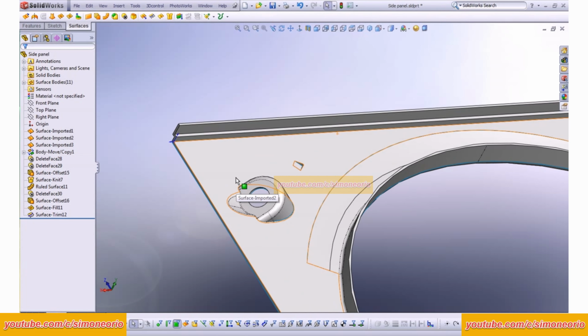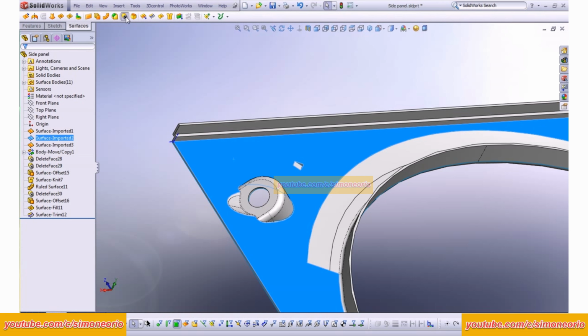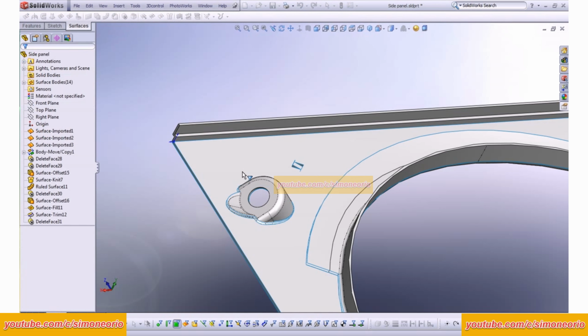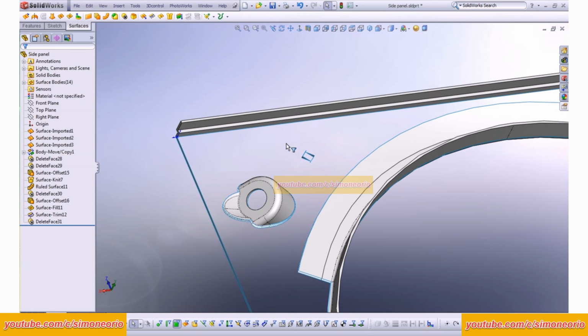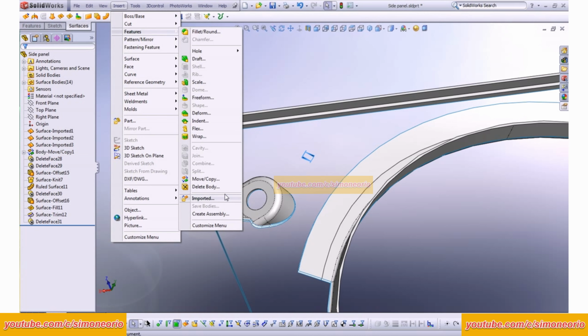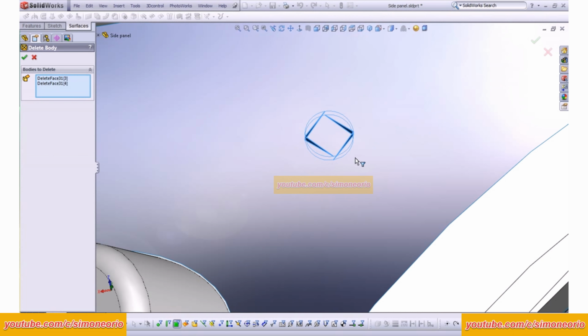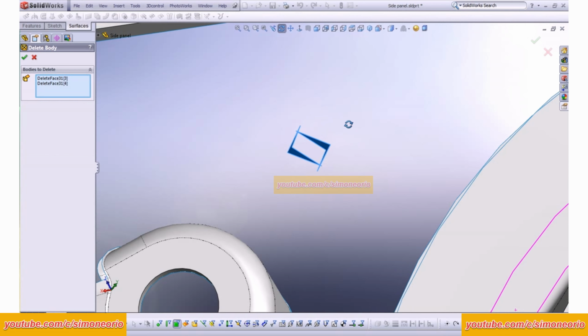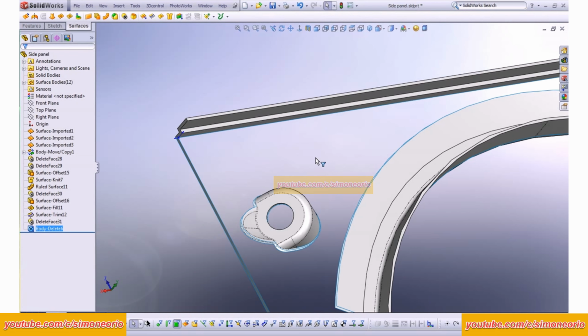To fix this, you need to delete this face. And we will hide the face we just made. So it just relieves these surfaces here. What we need to do here is remove these as a body. As you can tell, it looks like it's a circle, but when it was translated, they are still just diamond-shaped surfaces. Delete the bodies, and the hole's gone.